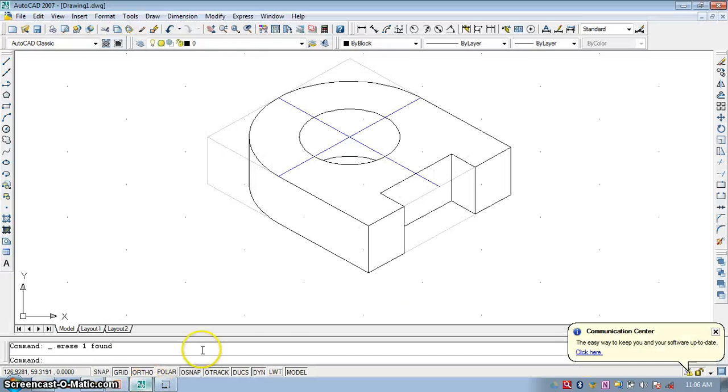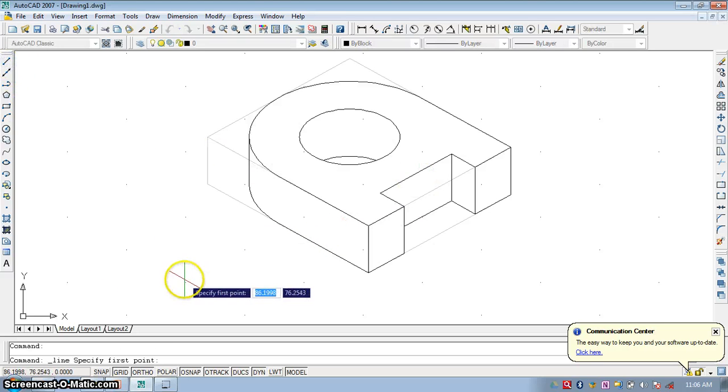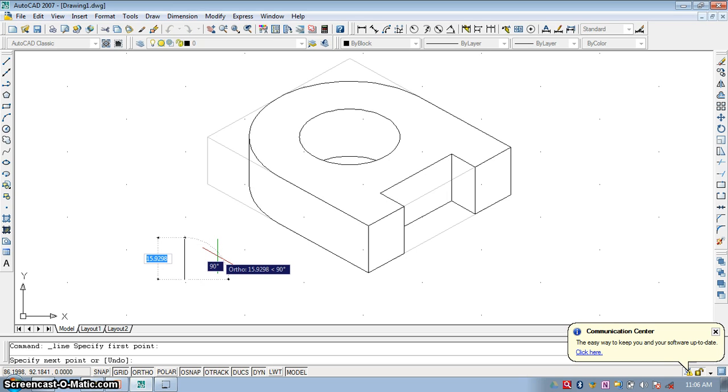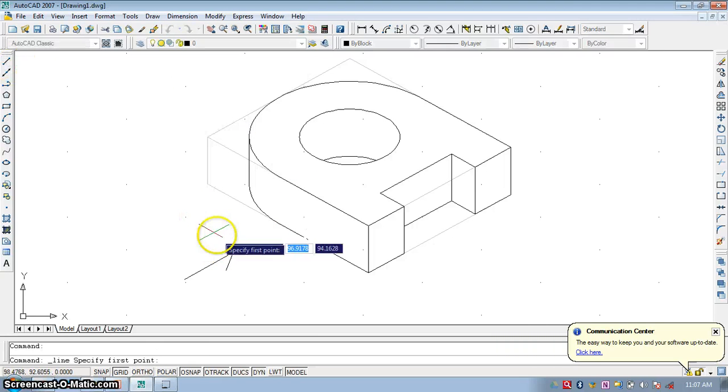You can observe here. So in isometric view, you are not supposed to give the dimensions. So dimensions are not required. Also you can remove the center line, and then you have to give the arrow for the front view direction. So the arrow would be in this front view direction like this. So the arrow should be like this. You can use this another line for this. So the arrow indicates that.